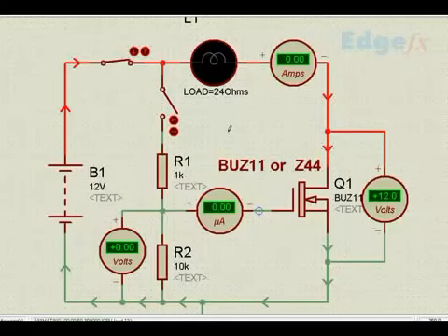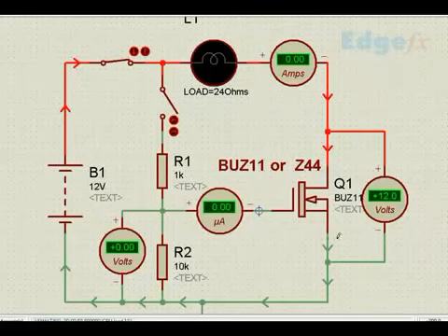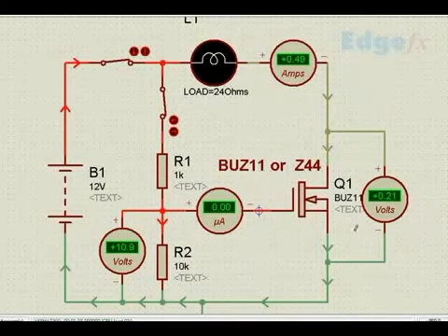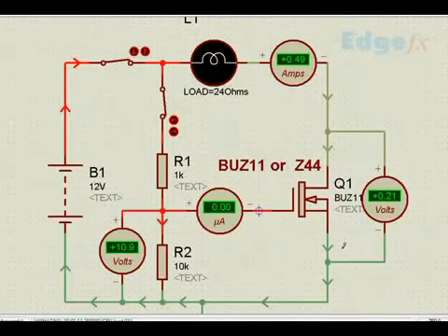Now the beauty is in how to use this MOSFET. This particular voltage drop is because of a resistance which is called RDS, that is, the resistance between drain and source. Because of the RDS, when the current is flowing, that voltage drop appears, and RDS varies depending on the type of MOSFET. It could be 0.001, 0.005, 0.05, 0.1, depending on the type, depending on the voltage, that you have to see from the specifications of the particular component.